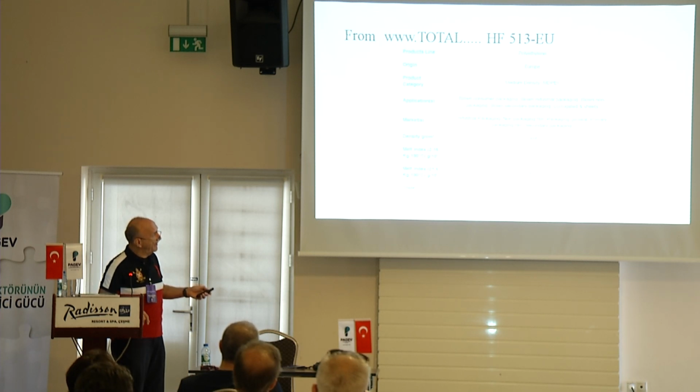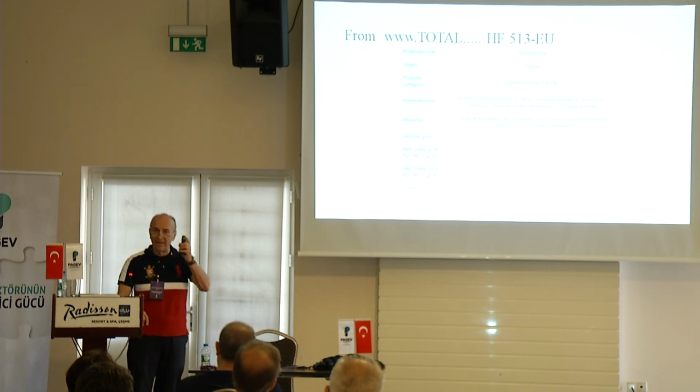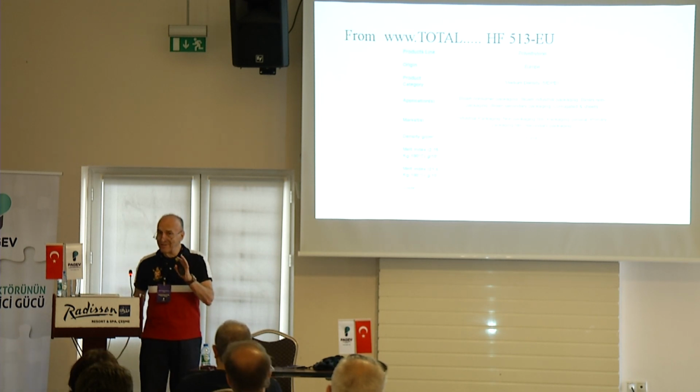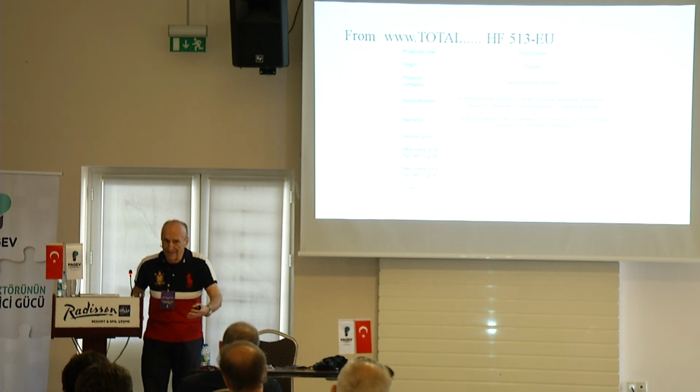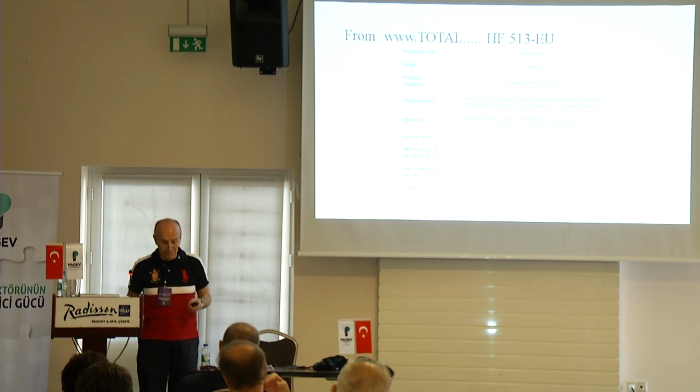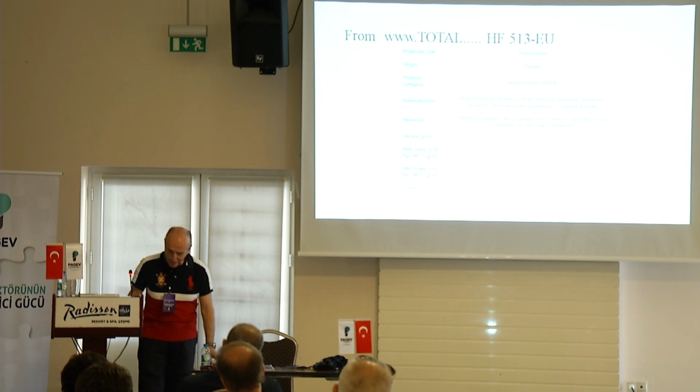However, the melt index from 0.15 becomes almost 100 times larger, which means you only put 10 times more weight, but you get 100 times more material, which means that the polymer is shear thinning. The more weight you put, the faster it goes, shear thinning property, which is very, very important.